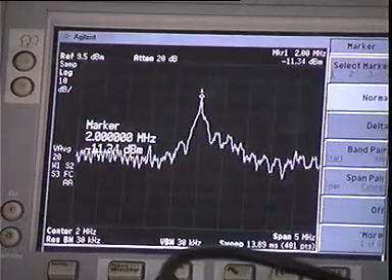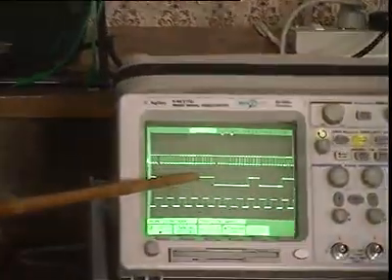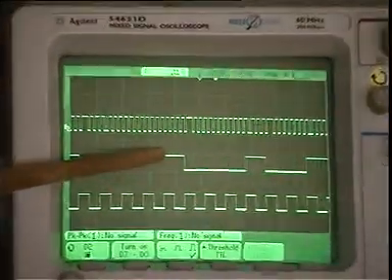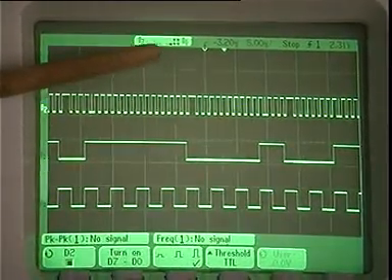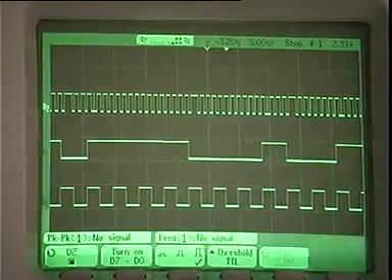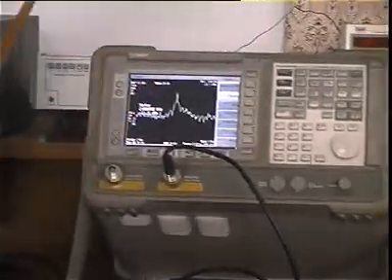So why is it sinc spectrum? Because your baseband signal is rectangular in nature. Because it's rectangular in nature, the spectrum will be a sinc square spectrum. But since I am putting in a carrier of 2 MHz, this sinc spectrum will now be centered around 2 MHz.